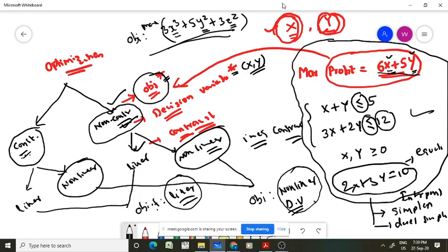Economic load dispatch will come under non-linear, sir. Yes, it is a non-linear optimization. Square is there, right? Yes. You have to minimize your total cost of generation, where the cost of generation depends upon your fuel cost, that is aP squared plus bP plus c. The square terms are available, which are non-linear in nature. So it comes under the non-linear optimization problem.